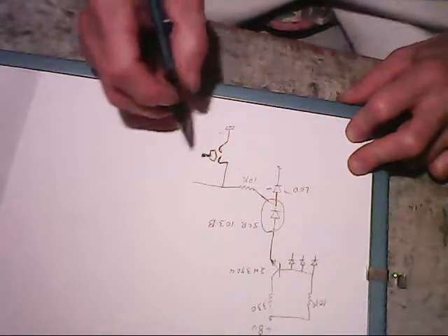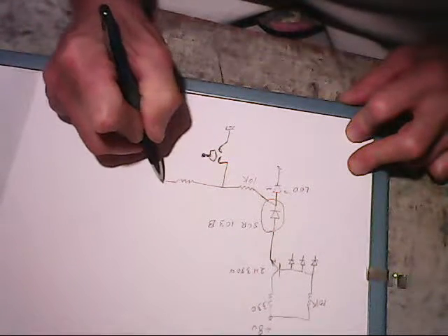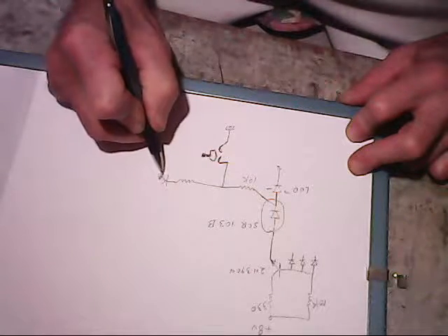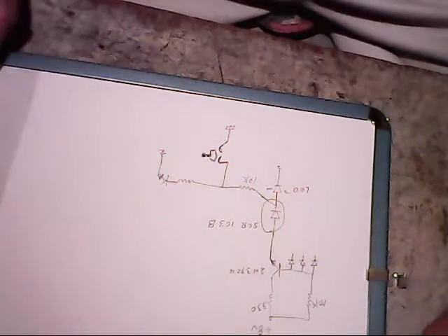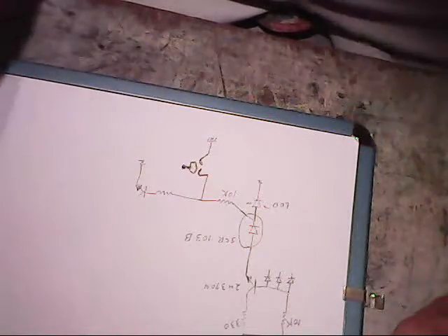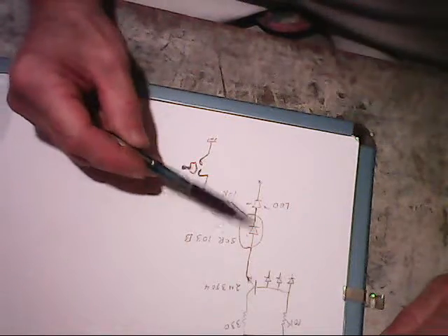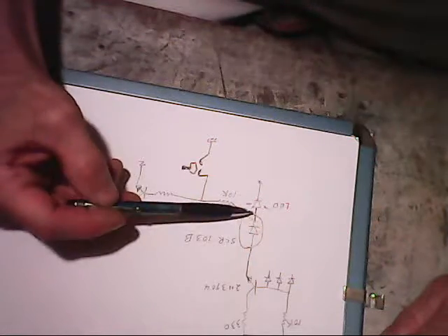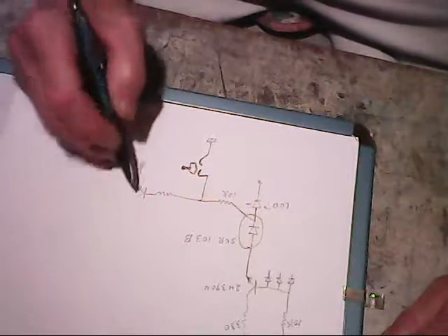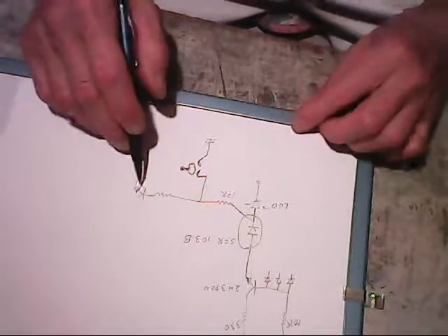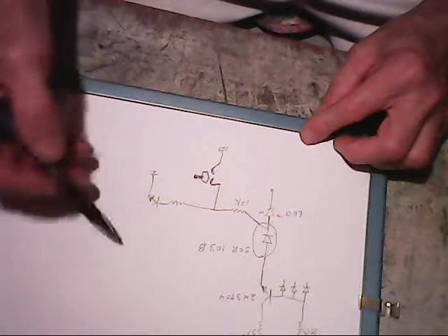Okay. So what we need to do is turn on another device. Let's go with an NPN transistor, and let's put its emitter to ground so that we can be sinking current. And as I've been saying before, I've been using sinking and sourcing kind of backwards here, but the load is here on the anode side of the SCR, so the SCR and everything above the load here would be sourcing current through the load. Okay, this transistor here is going to be sinking current, because it's going to be sinking current to the load up here.